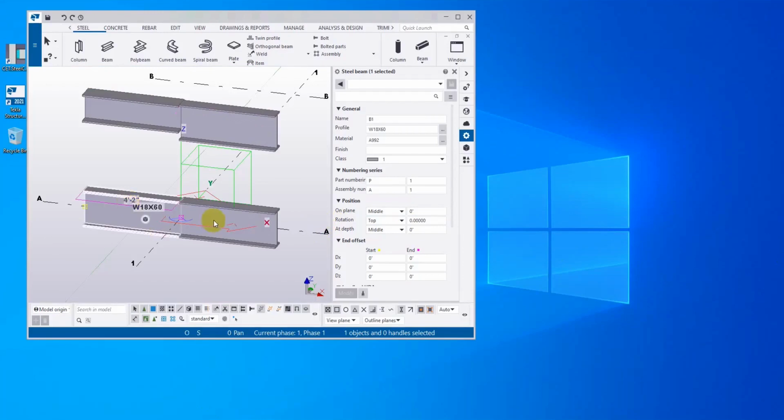In Tekla, Beam B1, B2, B3, and B4 have been created. Remember, for a beam splice connection, the top elevation of the two beams needs to be the same. The names of these beams are crucial because our software depends on them to establish connections.